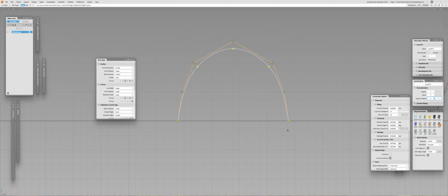We already discussed edit points. The reason why this CV is here and not here, and this one is here and not there, or vice versa, is because of a uniform distribution of the vector nodes. It is distributed along the domain uniformly. So the distances in the domain, for example from 0 to 1, like 0, 0.25, 0.5, 0.75, 1, in parametric space, are absolutely uniform.